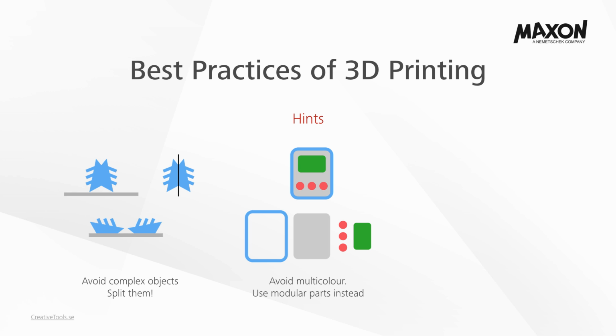The holy grail of 3D printing seems to be multicolor objects. There are several technologies that allow you to achieve this, but there are far too many disadvantages involved. My best advice to anyone who wants to print objects with colored parts is to separate them with Cinema 4D and 3D print them individually. These can then be put together with glue or snap fit joints. Doing so gives you far more advantages than a single 3D printer with color features can give.